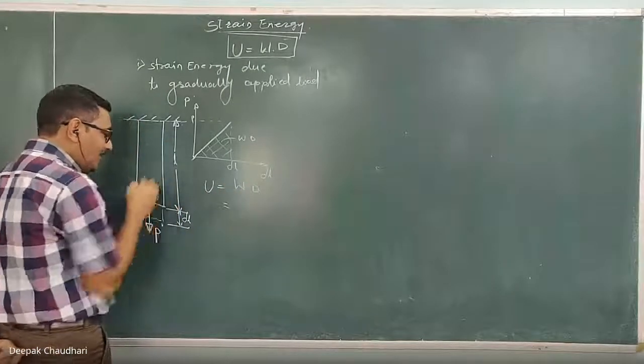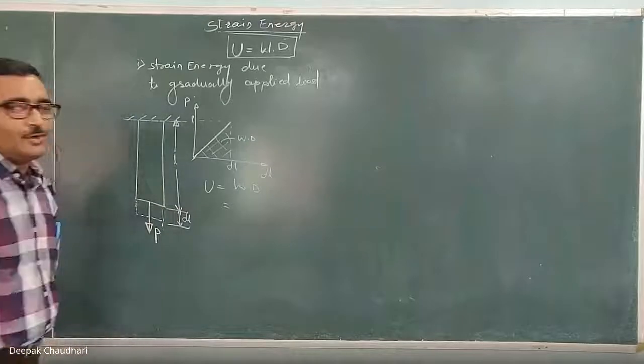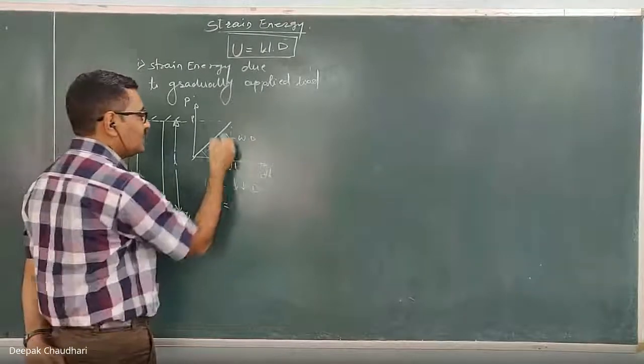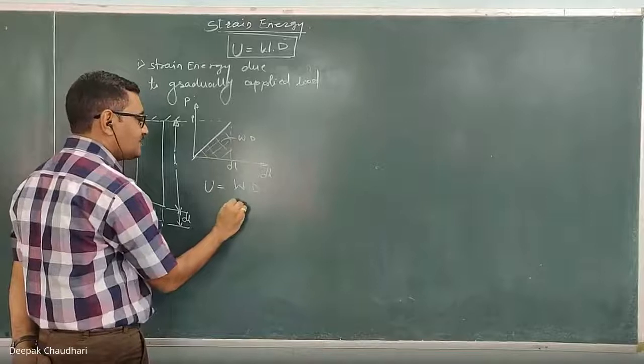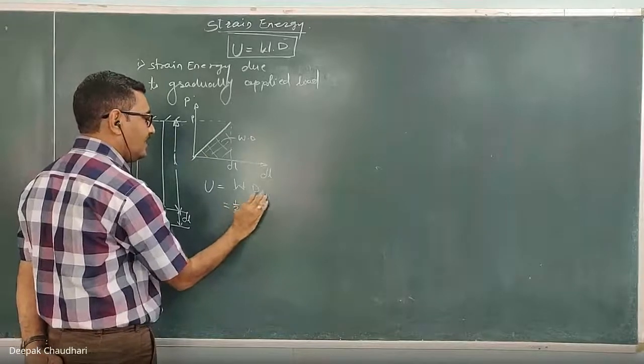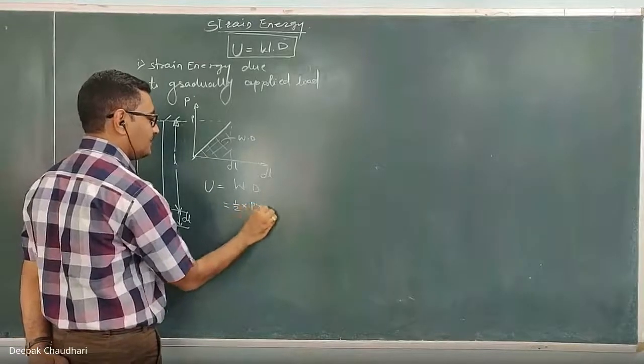When the load is applied gradually, and because of that the deformation is delta L, this work done is equal to the area under this graph, which is equal to half into P into delta L.